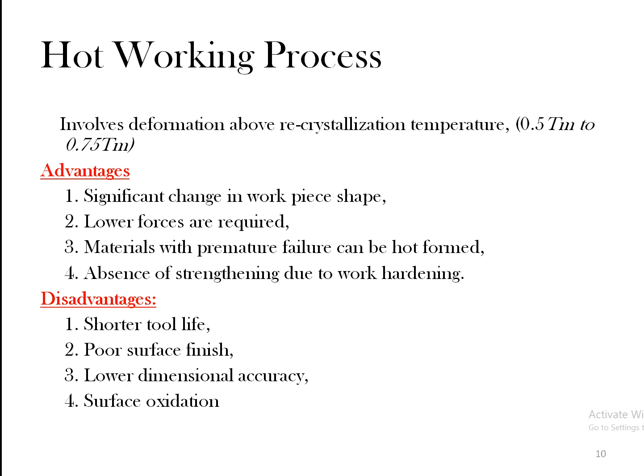The main disadvantages are that you'll get a poor surface finish compared to the cold working process. So finally, you'll have to do some machining in order to use it for other applications. The dimensional accuracy will be lower, and it is subjected to surface oxidation. Since it is in a heated condition, the tendency to react with oxygen is higher, and hence it produces surface oxidation.